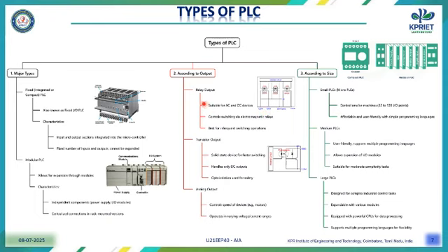Okay, the relay output consists of various relay modules. This is actually the transistor module, transistor output. Then this is actually analog output. We can control the output voltage of the analog output. So the relay output is suitable for AC and DC devices. Control switching via electromagnetic relay.